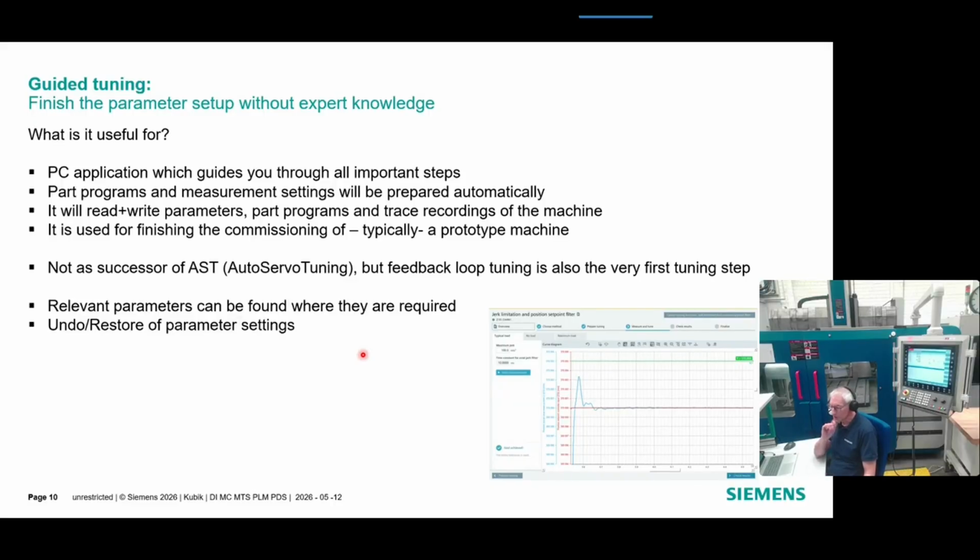Yes, so especially when the machine builder does service on the machine and changes parts of the drivetrain, then it's useful, for example, even to relearn the values for the friction compensation, but also to check stability of the feedback loops. And if there's really a very different situation to the commissioning, then it makes sense to check acceleration limits too.